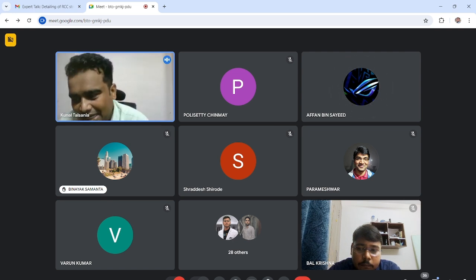In all the versions after 18 (18, 19, 20, 21, and now 22 will also come), they have made it so that you only have to enter the value of G, and the software takes all the other values by itself. So you only have to enter the value of G, that is 9810. You have to just assign 9810 for the initial scale factor, then first run your model, and after that